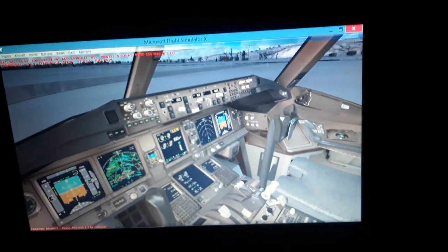We have also other aircraft flying around our own aircraft, as you can see over here in the navigation display. You can see other aircraft using the ADS-B and ATC transponder that transmits and receives our position and altitude, and also receives from other aircraft the distance, the difference of altitude, the direction and the airspeed, using the TCAS system, the traffic collision alert system, that also generates warnings in the navigation display. So it's a passive radar. You can see other aircraft flying.